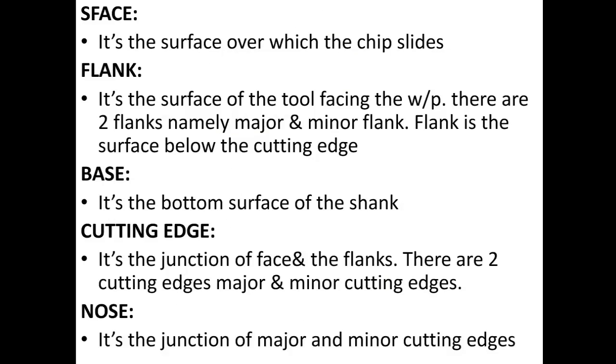Face, it is the surface over which the chip slides. Flank, it is the surface of the tool facing the workpiece. There are two flanks, namely major and minor flank. Flank is the surface below the cutting edge. Base, it is the bottom surface of the shank.